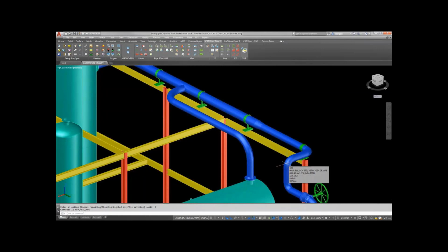I'm just going for this replace comps command, where I'm selecting the elbows. So the replace comps command is the command here. With that, I'm making the selection of this elbow. You see, I'm choosing the window for making the selection, and then for making the change. Then you choose what things you want to change in that.